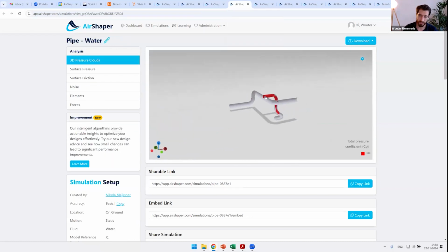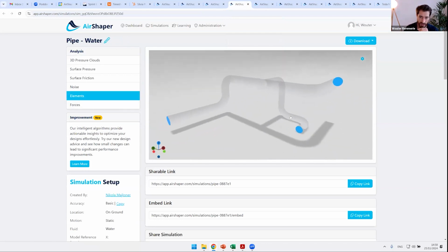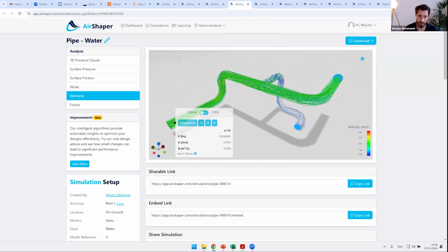You can also do internal flow simulations. And when it comes to automation there, for us, it's really important that you just need to set up a simulation with one click, and also the post-processing that you see here, which behind the scenes is using ParaView to a large extent, automatically shows you the streamlines going through a certain inlet or an outlet in the simulation.